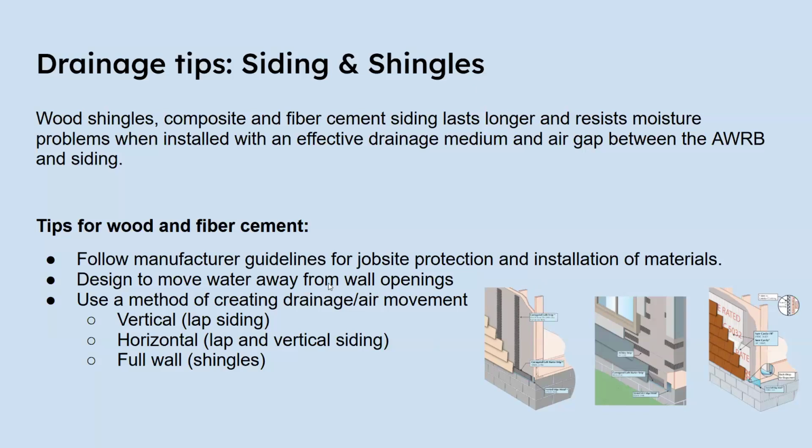Again, one of the main reasons the vertical strips or the horizontal strips are used is to keep the cost down. Typically, the cost of installing drainage mat is between $1 and $2 a square foot. With strips, it can be 30 cents to 75 cents a square foot.